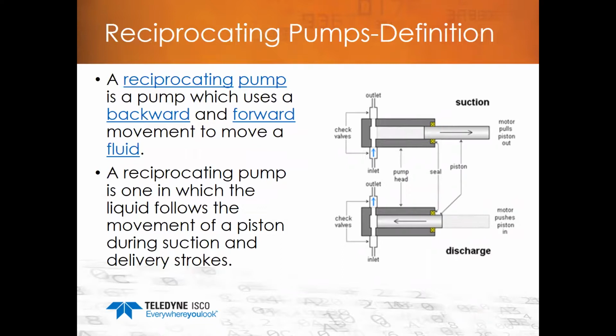It's really just a stepper-driven gear that pulls back the piston, and you'll see in the diagram there, it'll pull the fluid in the inlet on the suction phase, and then the next movement is the discharge, where the piston pushes the pressure back out and pushes the fluid out the outlet. And you have check valves that shut off the inlet and outlet during each time. Some of the drawbacks of reciprocating pumps is check valves can be kind of messy sometimes. But yeah, if you're looking at that technology, you've taken that into consideration in your application design.